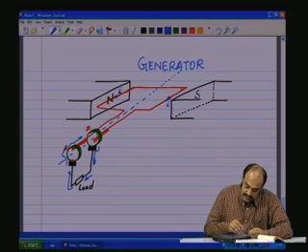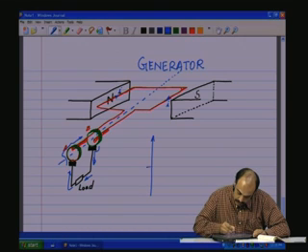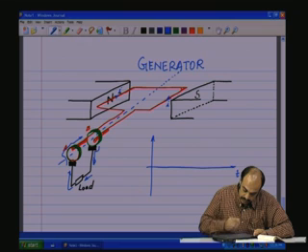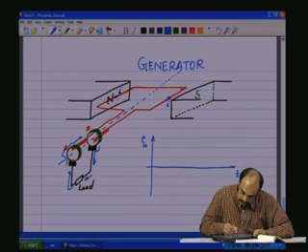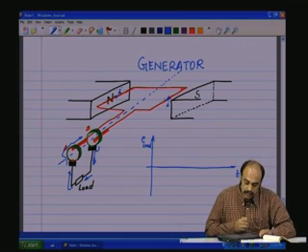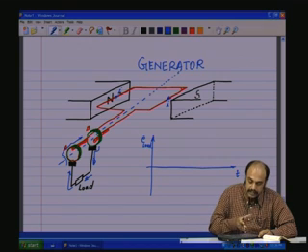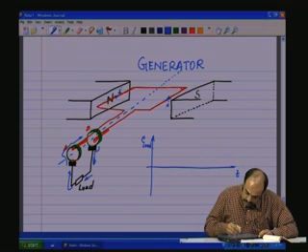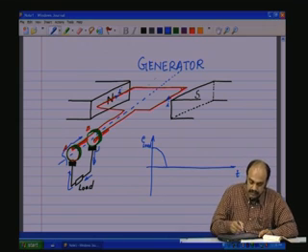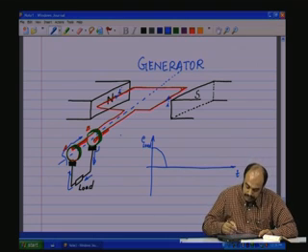induced output here. So, as the whole coil is rotated, we see that the voltage across the load, E load, which is the induced EMF across the brushes, starts with, in this position, a maximum, because the north and south are going to produce these aiding currents, and as it starts rotating and takes an orthogonal plane, this is going to pass through 0, because when the coil is in a plane perpendicular to the plane which is right now shown, it will be 0, because there is no flux in the perpendicular plane.